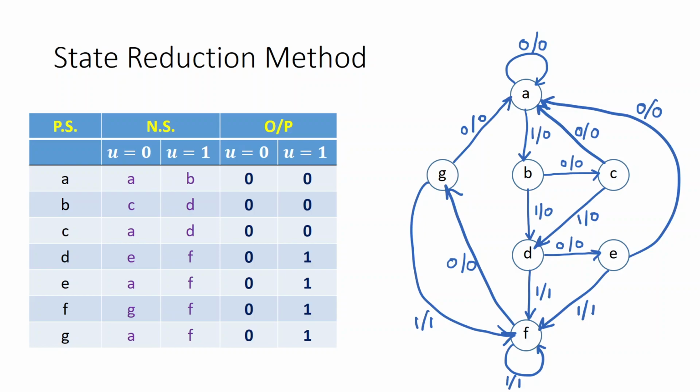Okay, so in which states are the next state and output combination same? So let us see. I think this one, you see, notice the next state is A, F and output is 0, 1 for your inputs 0 and 1. So similarly here also you see A, F, 0, 1. I think these two are the duplicate states.